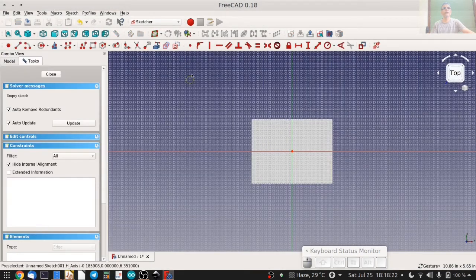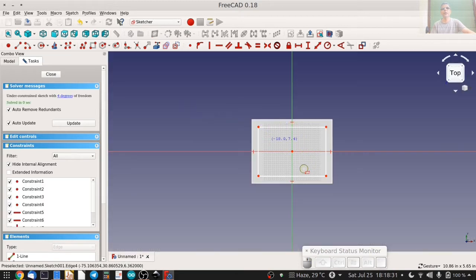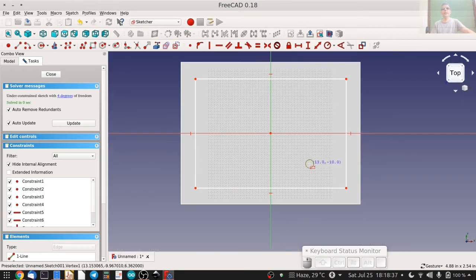So click OK, and you get back to Sketcher, and we can now make another rectangle here. But now we know that the wall thickness of this enclosure needs to be 0.1 inch. So this rectangle is going to be 0.1 inch shorter than the outer rectangle on all the 4 sides. Now we can do that using the outer rectangle as references. And that happens using this icon which says create an edge linked to an external geometry. If you click on that, and if I click the left edge and the right edge, that provides me the 4 corner vertices of the bigger cube as references. I can then press escape to get out of that mode.